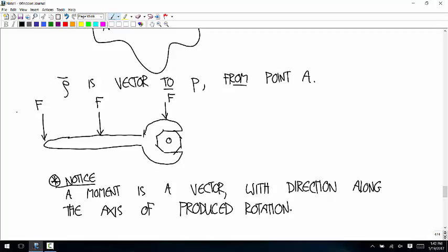And if the thing isn't rotating, like in statics, nothing's going to be rotating. Imagine the rotation that moment is trying to cause. So even if this stays stuck, you're applying this force, but that's not going anywhere. That moment's still trying to produce a rotation about an axis into and out of the board. And so the direction of that moment is into or out of the board.